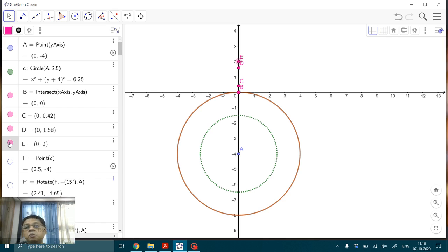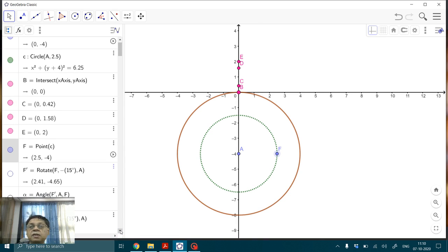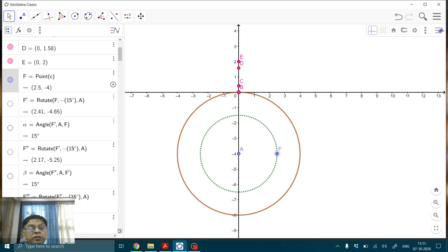Now what we are going to do is mark a point F, which is going to be along the horizontal. So AF is basically the reference line from which, remember that the translating axis is going to be here. So we start from this point. Earlier, you remember, in the radial case we started from the vertical and marked 15-degree increments. Now here in the offset case, I will have this segment AF. So F is basically the horizontal line, which forms my reference.